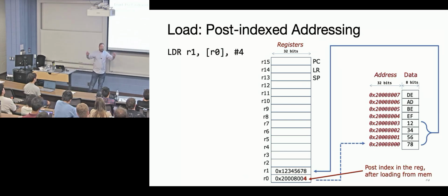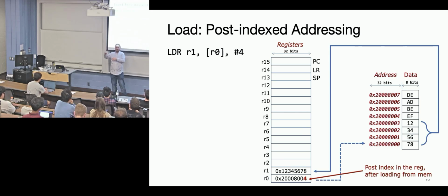I don't know why, but they really wanted us to have this functionality. And when they were making the ISA, they said, man, this is really important for us to have. It is important to think about how when you start doing things like setting up peripherals, you're going to have base registers, and then you're going to have the offset. So port A on your microcontroller will define how GPIO works. Port B does exactly the same thing with different pins. So now you can use exactly the same code, and all you have to do is change the base address, and then all the incrementing will allow you to do the same functionality on either side. So there are good compiler reasons, good code efficiency reasons why you'd want to have this.